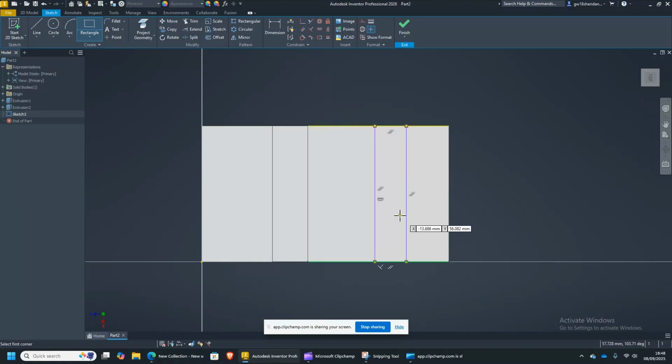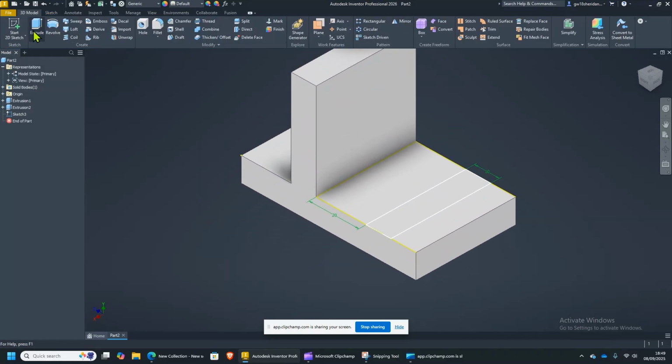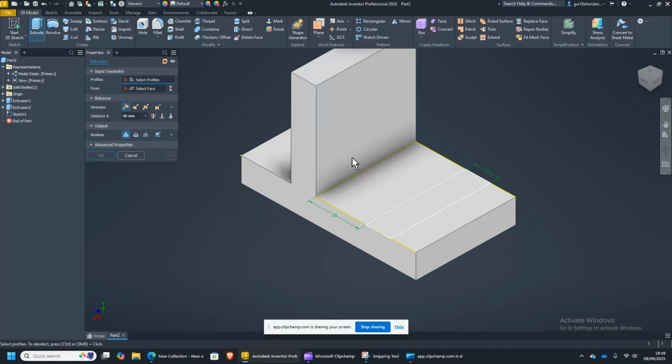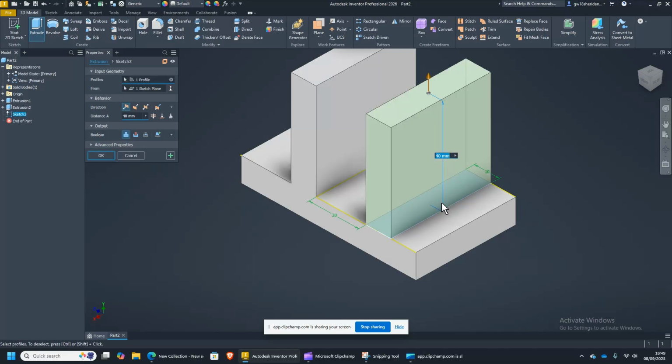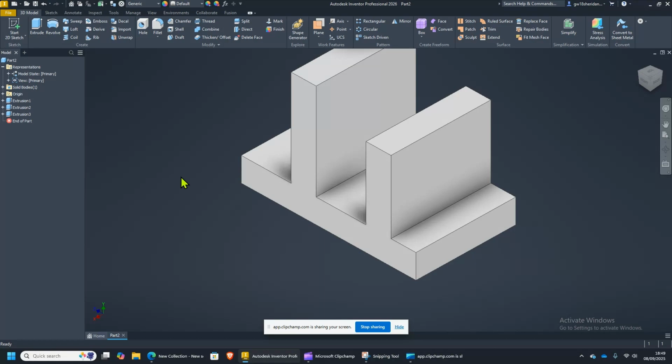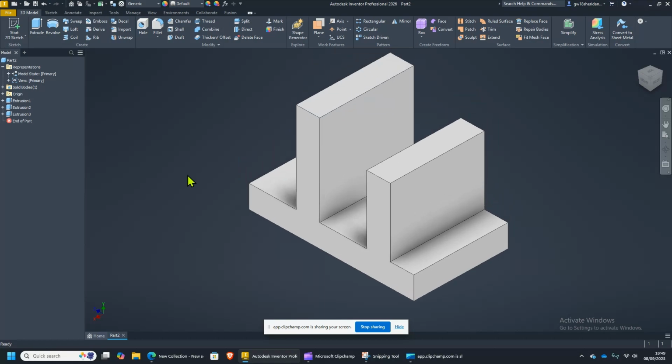and the edges over there, click there, and put in our sizes again with our dimension tool, and we'll tell it that between there and there is 10 millimeters, and that between that point and that point there is 20 millimeters. You can finish your sketch. We can extrude, and again we have to choose which rectangle is it. It's this one right here, and this time we're only going up 30 millimeters. To fit it all on screen, I'll hit the home key right there.